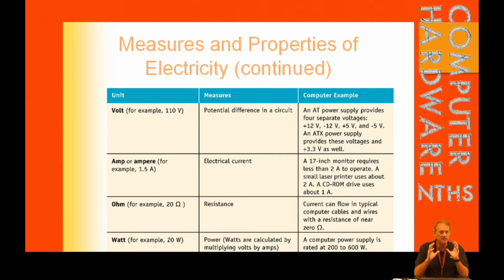So that's the definition of electrical power. If I've got an electrical circuit running on the wall, and I plug this in, if there was no amperage in it, it wouldn't have enough to power this and get out the total power that we need for our laptop. And by the way, that's why some laptop power supplies don't work on some laptops. If the wattage of this one is too low, it can't put out the total power that the laptop needs. You guys have laptops that need 90 watt power supplies. It has to be 90 as a minimum. And we have 65 watt ones, which, if you plugged it in, would charge your battery just fine. But your laptop would run terribly because there's not enough power to run it at the speed that it's supposed to have. And we'll talk more about the wattage requirements of laptops in a little bit.